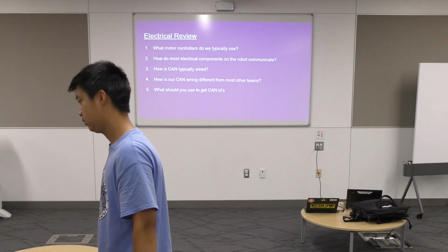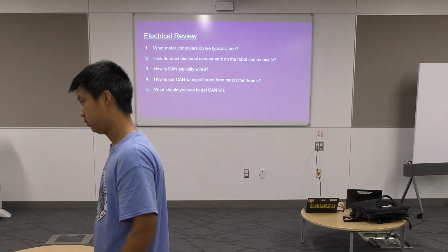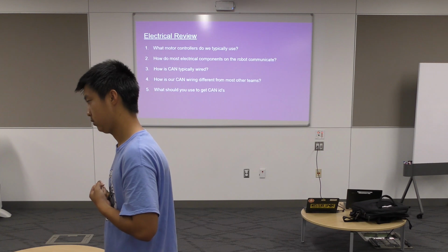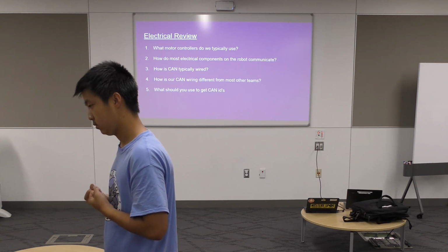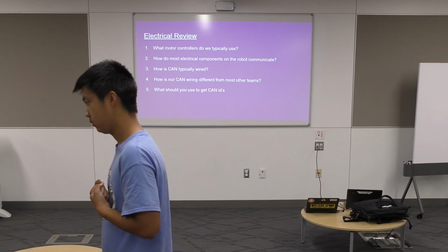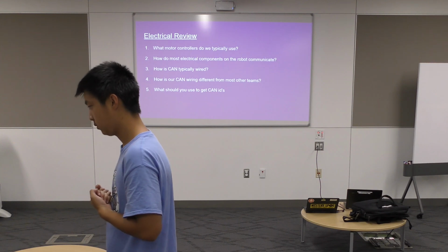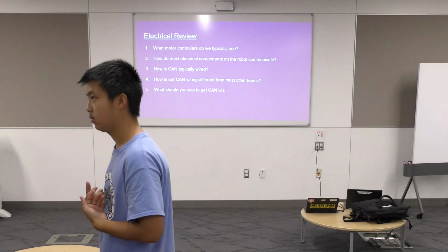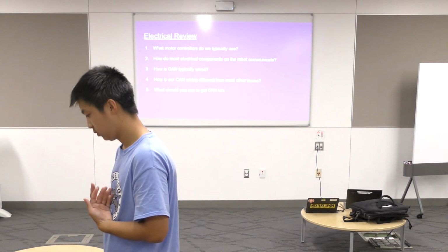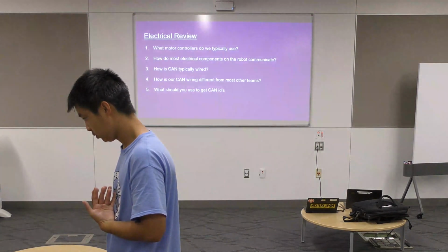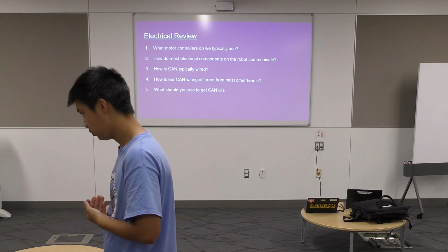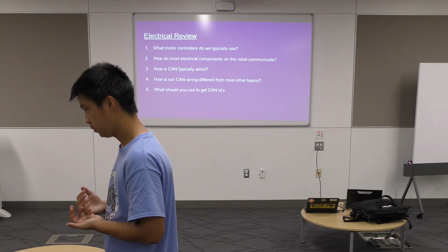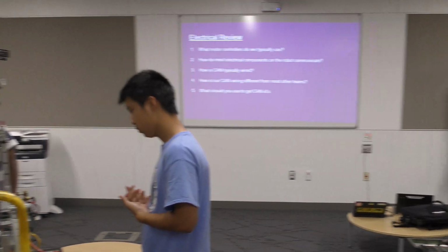A relative encoder zeroes out where you start, and it counts the ticks after you start moving. But an absolute encoder like this doesn't zero out when you power on the robot. It remembers where it's been. That's super useful for setting start and stop positions, so you don't have to reset it every single time. Let's say you accidentally power up the robot and the claw's out here, it'll still remember to go back to its initial position. So that's one of the sensors, the linear actuator, and that's pretty much all the important electronic stuff on the robot.